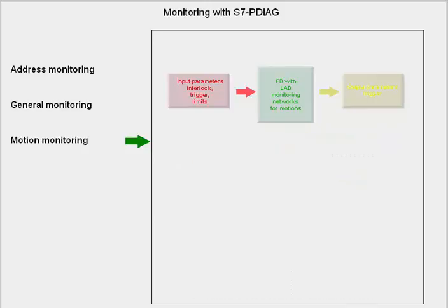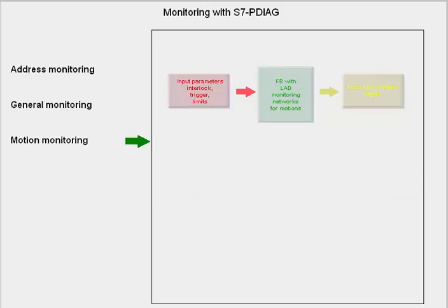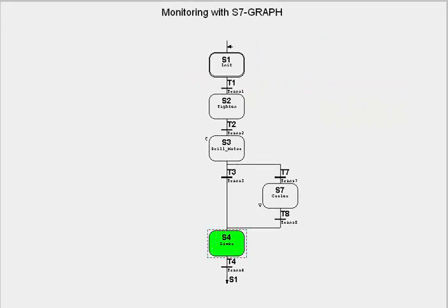The standardized data structures make it possible to incorporate ready-made HMI masks, such as the manual operation mask, without having to do any programming. This option for generating standardized multiple-use monitoring blocks, which also adapt their instance-specific message text automatically, is a great potential for streamlining in engineering. With the S7 Graph language, the option for process diagnostics is already an integral part of the engineering tool.